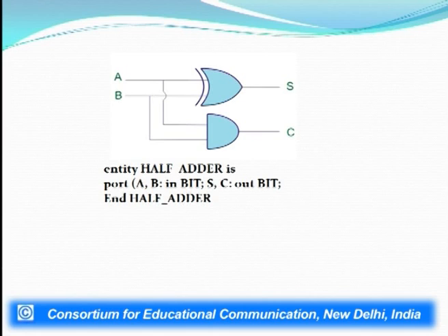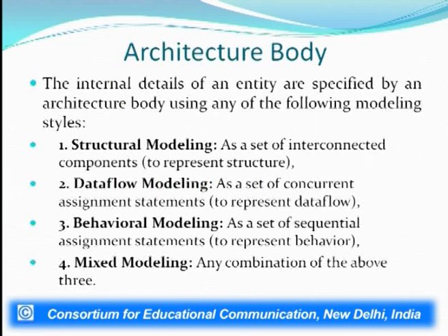Then I end my entity by saying end half underscore adder, which is the name of the entity. So, the entity that has once been initiated has to end by using the keyword end followed by the name of the entity. Now, coming over to the architecture body.